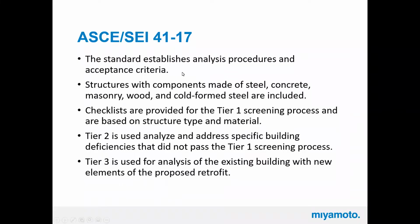seismic hazard levels. You can pick your seismic hazard level, anywhere from a maximum credible earthquake to some kind of reduced design-based earthquake, and you can hit different performance objectives along the way. So it's a pretty useful and adaptable tool to use for different buildings and different goals based on the owner's or jurisdiction's requirements. It does sort out deficiencies, so we'll talk about that in coming slides, and, as I said, it establishes analysis procedures and acceptance criteria.